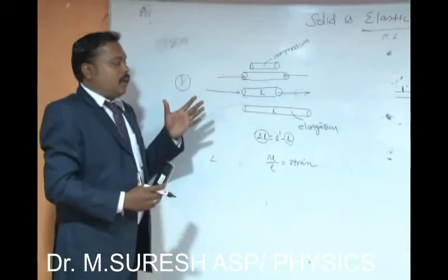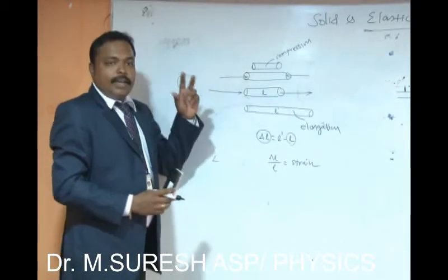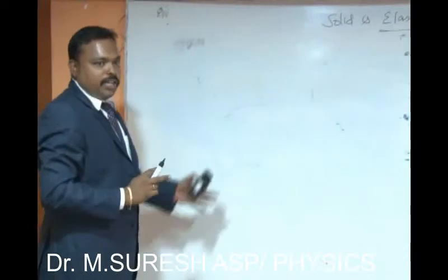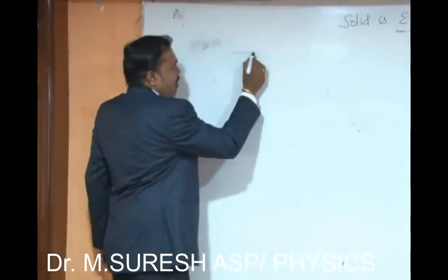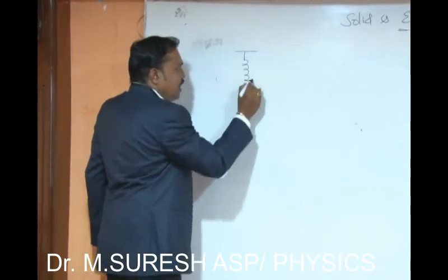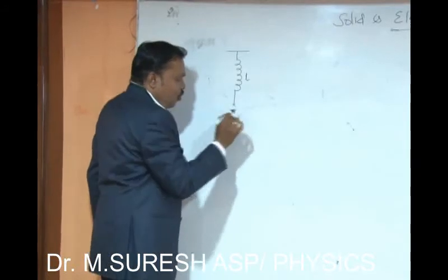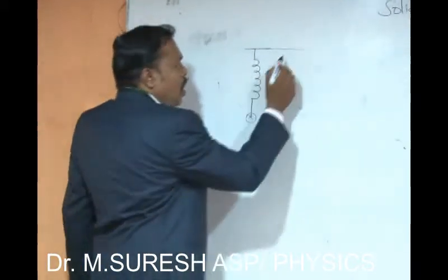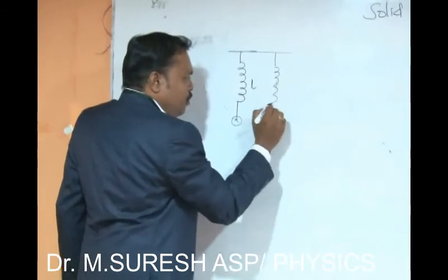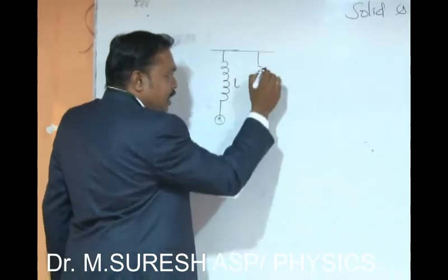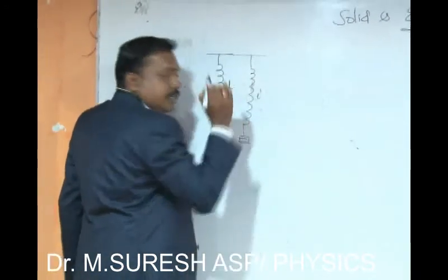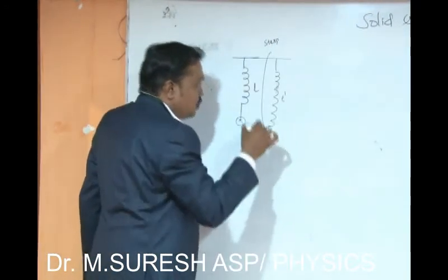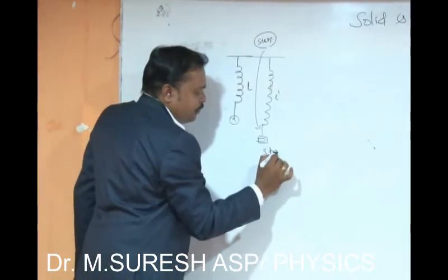To understand the relation between the stress and strain of a material better, let me discuss the expansion or compression of a spring with respect to the stress. Let me consider I have a spring which is originally at the length of L, right? I have applied no load. The load is the representation for stress, right? Now I am applying a small amount of load at the end. It results in the elongation of the spring. Now the new length of the spring is L prime, right? So here stress is causing the strain. The applied stress produces the strain.